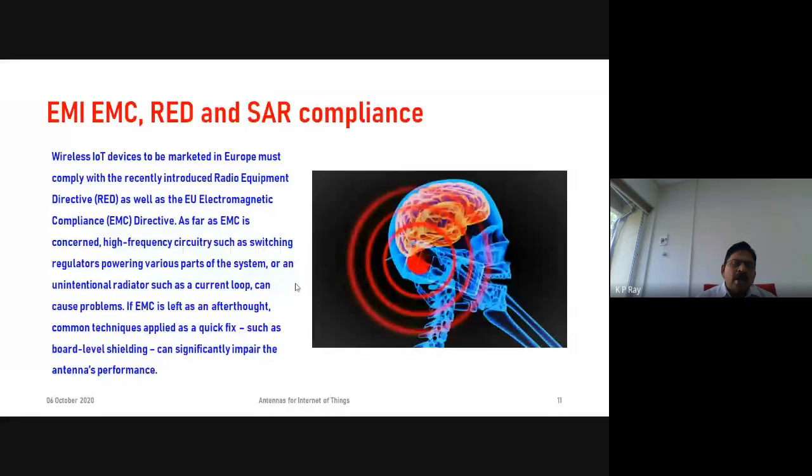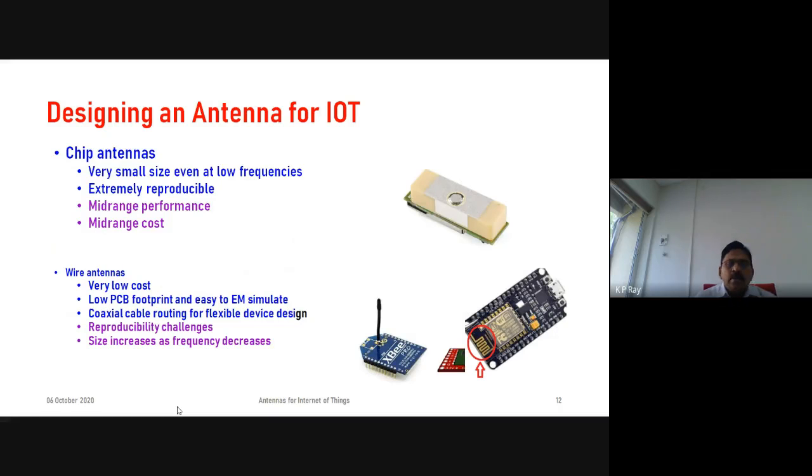So basically, your antenna should work in a very intense electromagnetic interference environment, and you should design your antenna in such a way that it works properly in a very high level of interfering signal. Before you use those antennas for your system, you need to test for compliance, whether harmonics are getting suppressed and whether your antenna is hardened. So that compliance has to be looked into.